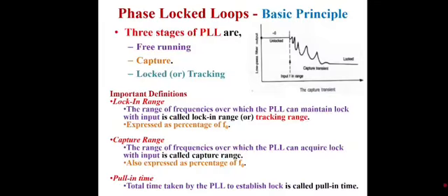The control voltage shifts the VCO frequency to reduce the difference between Fs and F0. When the process starts, the signal is in the capture range, and the frequency adjusts continuously until Fs equals F0. At this point, the system is locked.